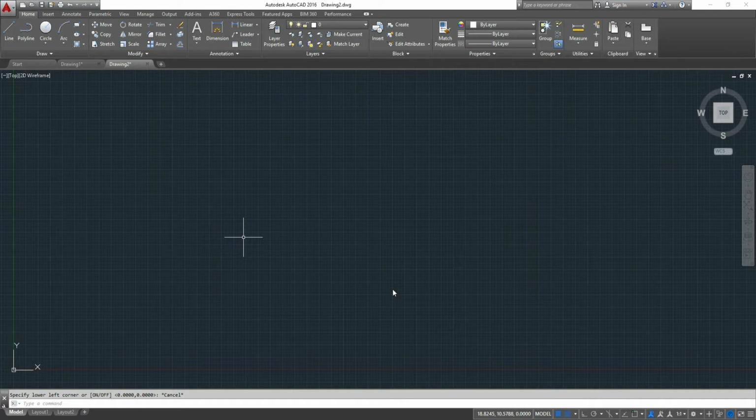And then you can enter them as absolute or relative. Absolute, you just enter them in, and the absolute coordinates will be relative to the origin. Relative coordinates will be from where you're at. Then use the at sign, shift 2, to specify relative.